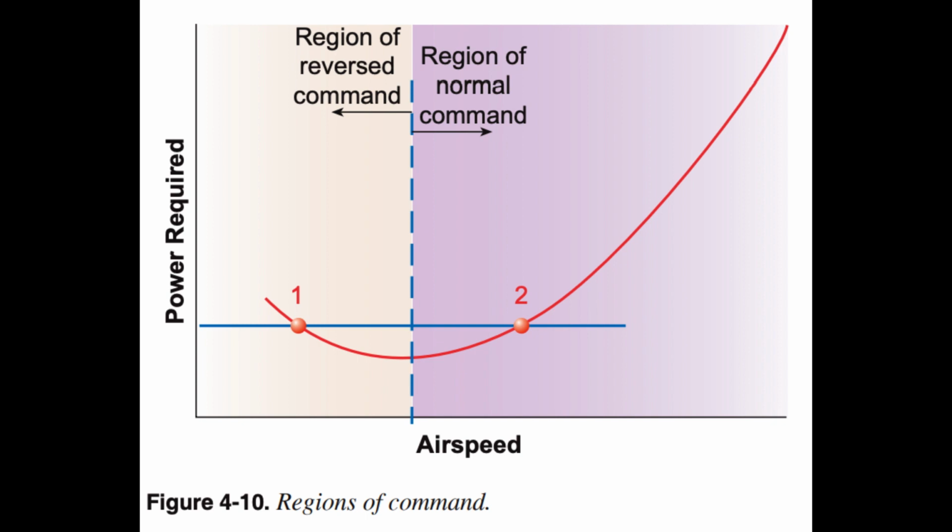This tendency toward instability happens because the variation of excess power to either side of point B magnifies the original change in speed. Although the static longitudinal stability of the aircraft tries to maintain the original trimmed condition, this instability is more of an influence because of the increased induced drag due to the higher AOA in slow-speed flight. Trim.